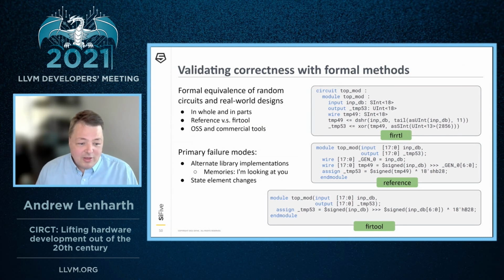If I have an alternate implementation of a memory, even if it's correct according to the spec, it is not formally equivalent. This is equivalent to taking two different C++ libraries and comparing the internal states of the implementation while it's running. They are not going to match, they are different. So on a case-by-case basis, you have to say, what matters more, the spec or the old implementation? And since Chisel is really a one implementation world right now, you have the other concern of how much designers are depending on particular implementation choices rather than the specification.